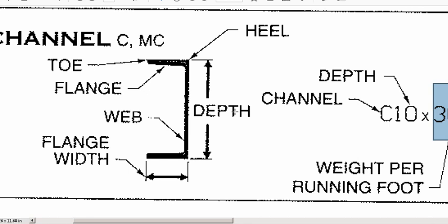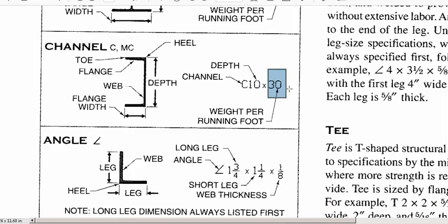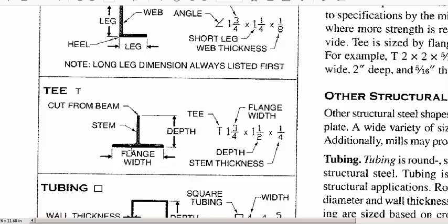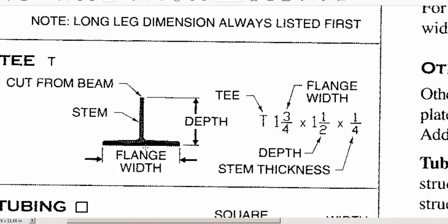While we're here, we'll go ahead and talk about another one though. That is the T-beam, or the T. We'll skip the angle and do it in a different lesson. The T is also sometimes used as a beam. You'll notice that its call out, you don't see this as much, to be honest with you, in steel fabrication. You see it, but you just don't see it nearly as much as you see C channels, angles, and W beams.